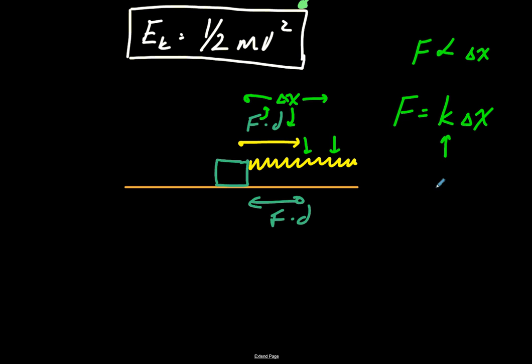This was the spring coefficient. It is a characteristic of a given spring, right? The more stiff the spring, the higher this value becomes, the more force we have to apply to squash it a certain distance. Think of the difference between a very light watch spring and the spring on a car shock absorber. The car one requires a lot more force, and therefore has a higher k value. This is measured in newtons per meter. The change in x is in meters. Those would cancel out and we get a value in newtons.